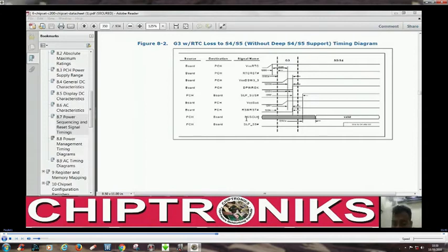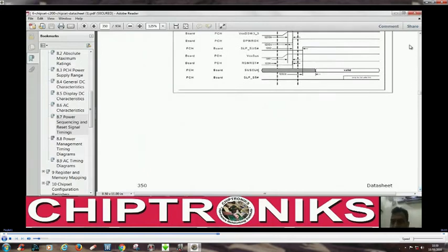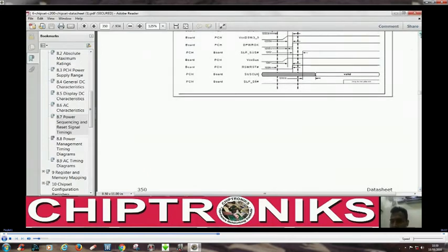And what does SUS clock mean? SUS clock means suspend clock. Actually, when the board is turning on, right now, when the SUS clock is generated, there is no clock generator, the clock generator has not turned on. As we have spoken earlier, the clock generator turns on last.